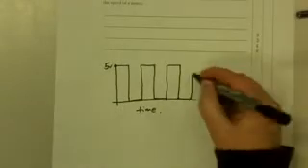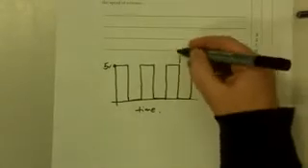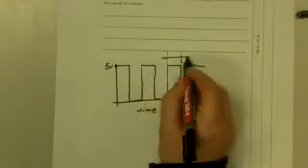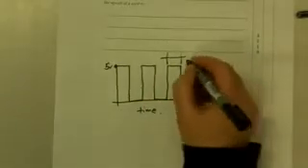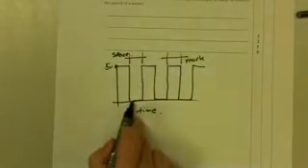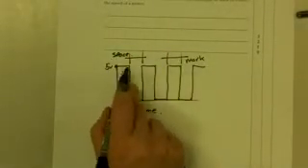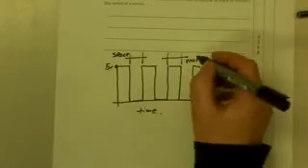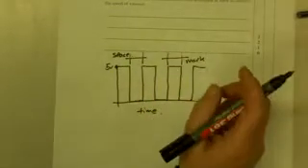And you need to label that pulse. That is the mark, and that amount of time is the space. Space is when there's no voltage, and the mark is when there's VCC, voltage output, 5 volts. The ratio between these two can control the speed.